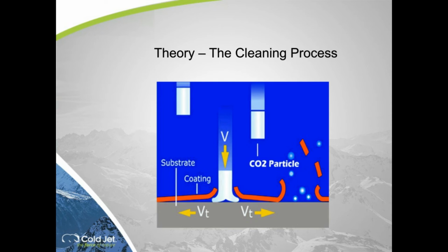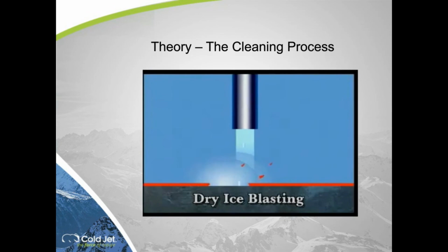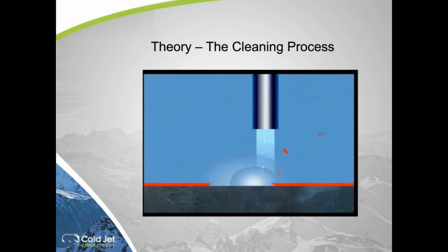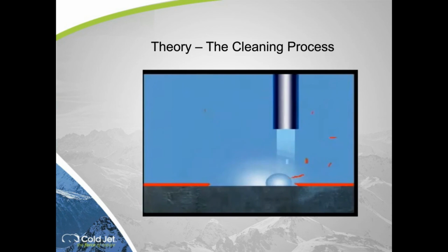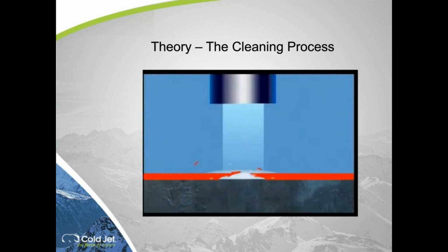The dry ice comes in, kind of a diagram here. You hit the contaminant, it shrinks it, it's cracked it, and then it expands. Let me just give you a quick video of what that would look like in a simulation. That is what dry ice cleaning looks like. The dry ice is accelerated at high velocities. It is impacting the contaminant. It's traversing. It is embrittling the contaminant. It is phasing back to a gas, and it is blowing the contaminant off. That is the entire process.